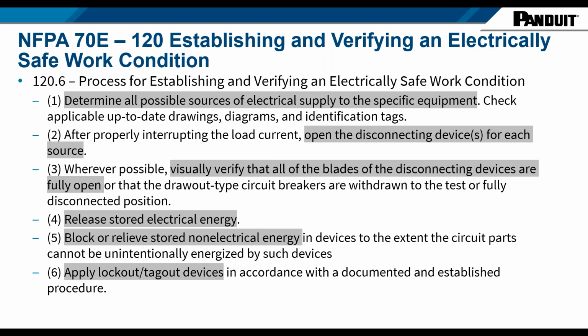Release any stored energy, right? That could be capacitors, it could be non-electrical energy in step 5. But release any stored energy in step 4. Step 5 is block or relieve stored non-electrical energy, right?